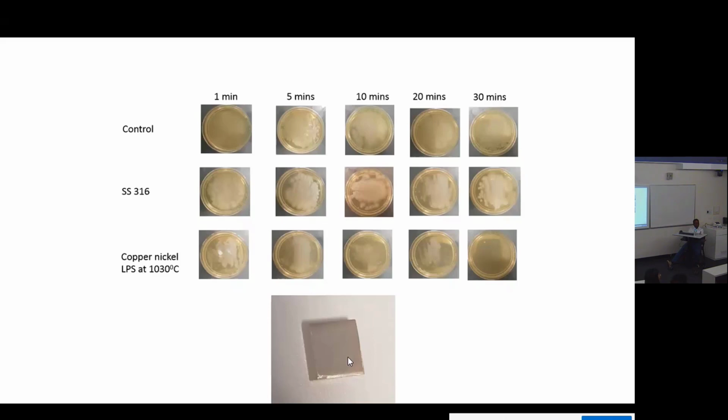So CSIRO, for example, do lots of very, very fine detail cold spray, and they'll do it on the micron level. So you typically look at like 30 to 50 microns, depending on the powder feedstock that we're using. But yeah, very different application from what we do. Same process, but it's like saying, there's lots of different types of welding, for example. All of them are good at different things, or all of them can be made to do different things. But the base technology is effectively the same. Yeah. You can, if you had nano powders, then you can run laser or electron beam.